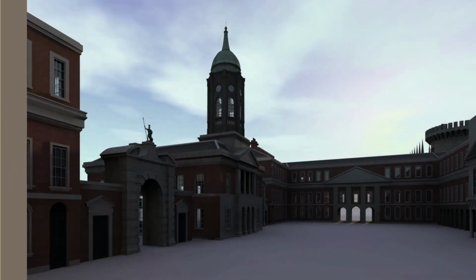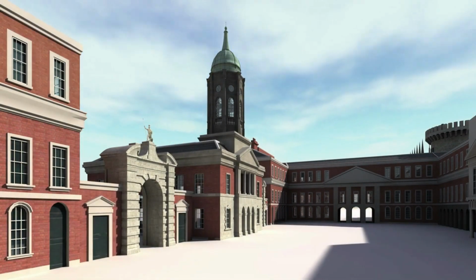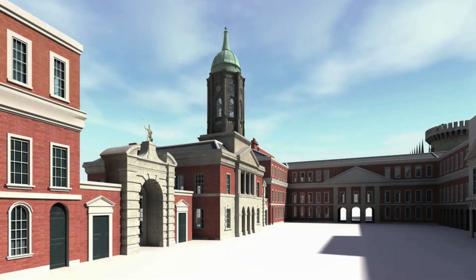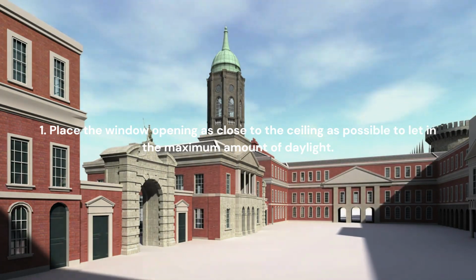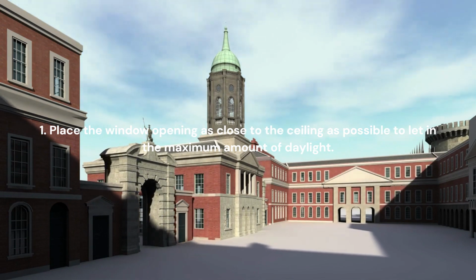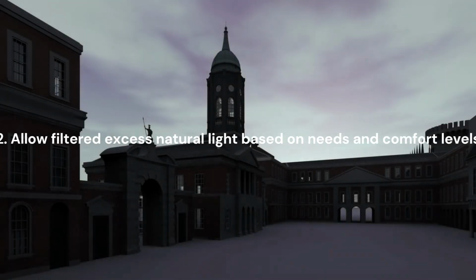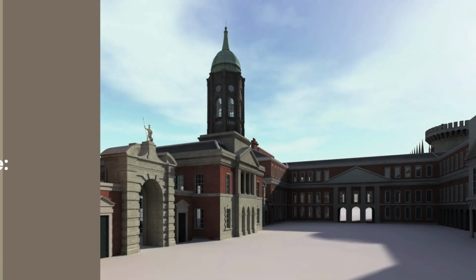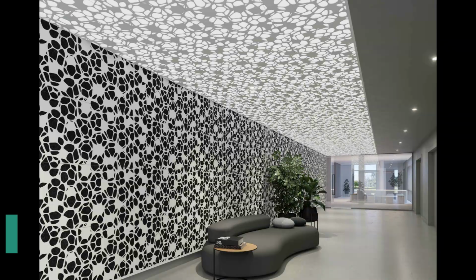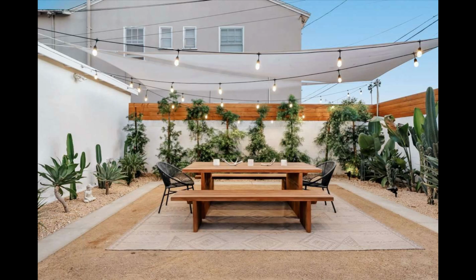5. Daylighting. In spaces where daylighting is of abundance, it's important to consider heat gains and glare while designing the spaces. Key design strategies. 1. Place the window opening as close to the ceiling as possible to let in the maximum amount of daylight. 2. Allow filtered excess natural light based on needs and comfort levels. Example: jali walls, perforated roofs, semi-open pergolas, partly shaded courtyards.